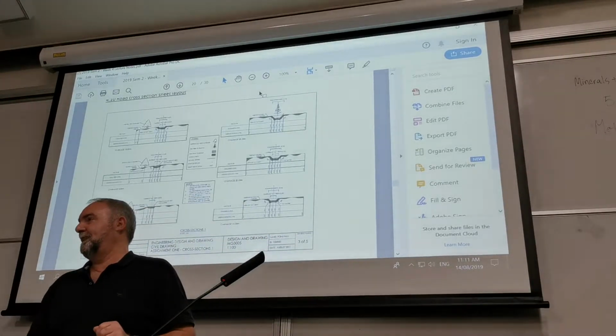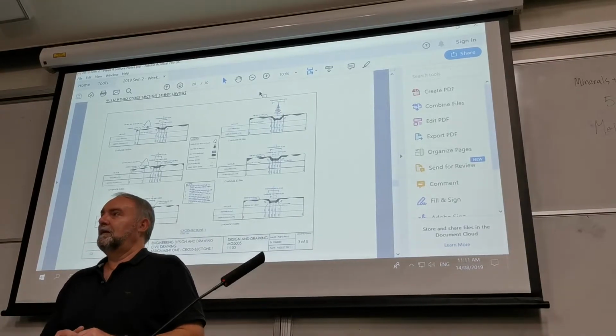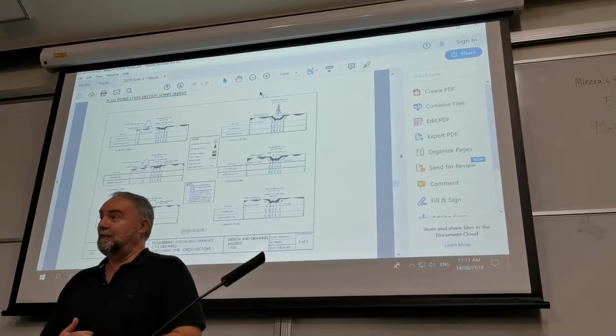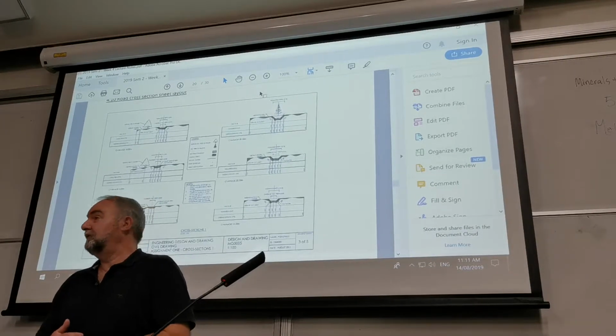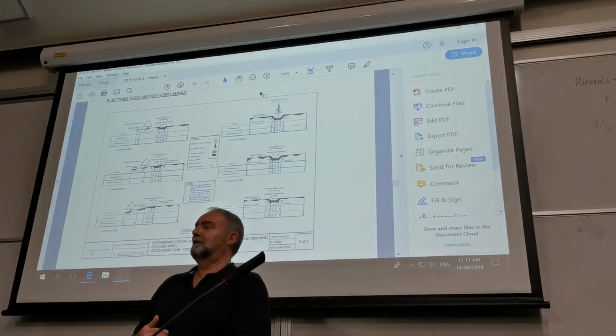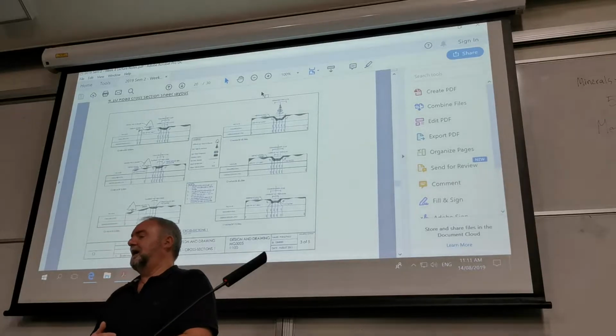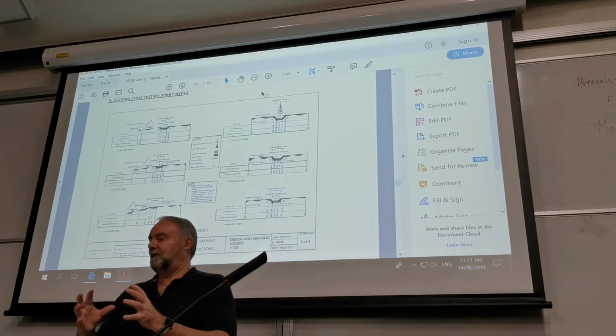Isn't the butterfly cut and fill type thing on assignment 1? No. Please don't draw that on the existing site plan. And please don't put your section marks on there either for the cross sections or long sections. Yeah, the butterfly wings, you will copy that to the side.